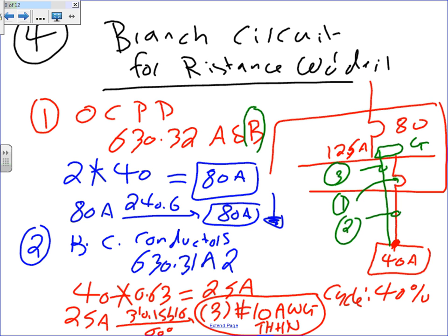Now, this is where you're going to do the check that we just talked about, guys. Any question about this? We're almost done. Yes, sir. Is there a reason why we use 3 conductors? Three phase. Do we get a neutral? No. Most likely you're not going to need a neutral on a three-phase welder. If you need it, you add a fourth conductor. Good point.